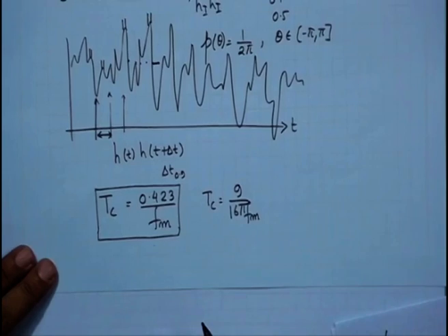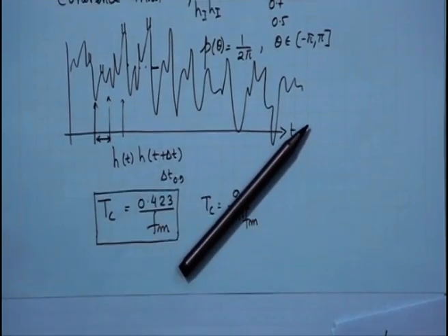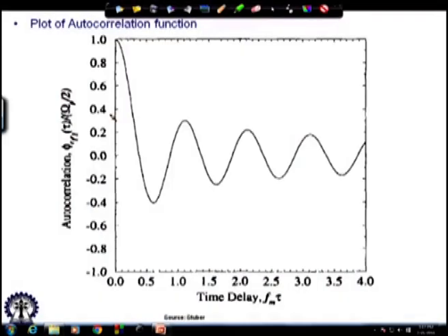This is again a rule of thumb, but what ideally should be done to calculate the coherence time is to use this particular picture, that is the coherence time relationship, where we have delta t Fm, and say that suppose I want 90% coherence time. I would go to 90%, read this particular point, and try to come to the x axis.